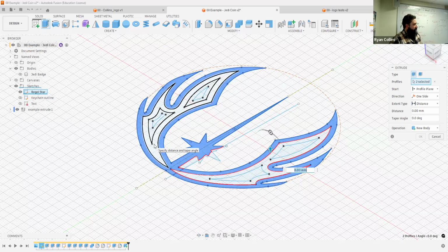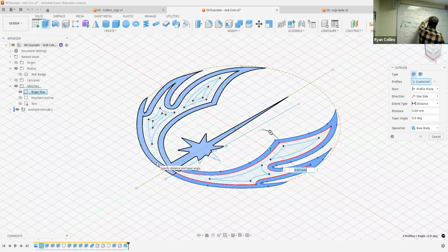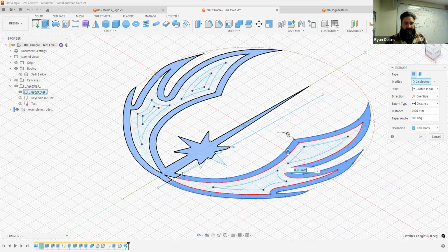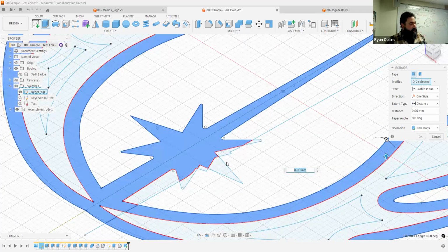If it's not a closed sketch, you cannot extrude it, because it means your points don't quite go all the way and you've left a gap. Until you close that gap, you cannot extrude what's inside of there. With this, also make sure you got all the parts, because sometimes if you draw lines, things like that, it will read that as a dividing line.